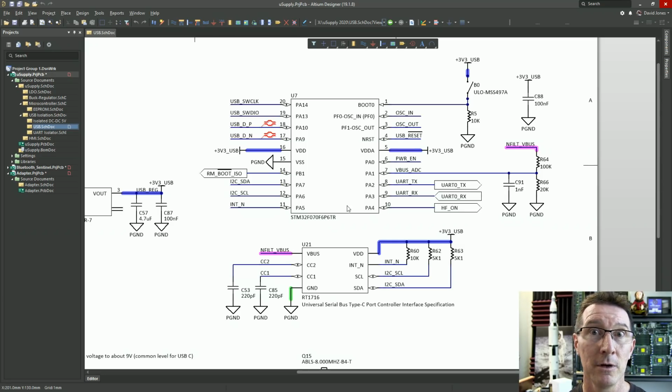The STM32F070 micro is very different depending on the letters you put on the end of it, and it's really freaking annoying. Anyway, in the hardware prototypes that we've built, we chose this relatively low-cost STM32 micro because we're also using an STM32 micro as the main control element on the isolated side. It's a little 20-pin TSSOP package, and it's got 32K of flash.